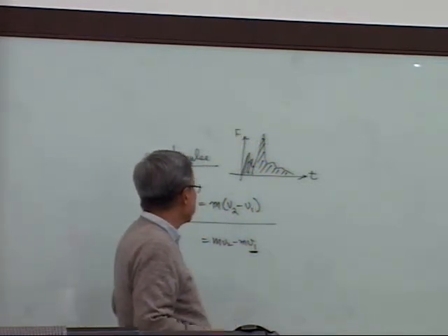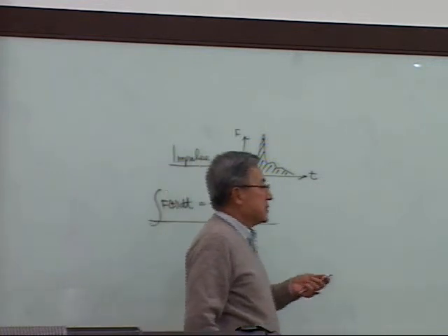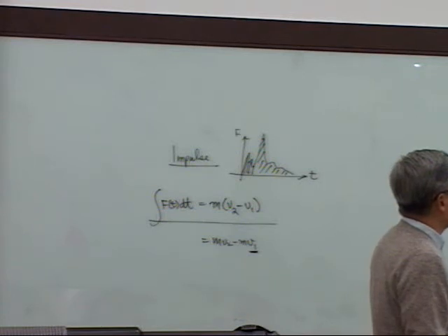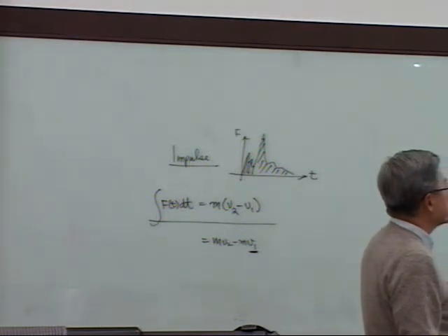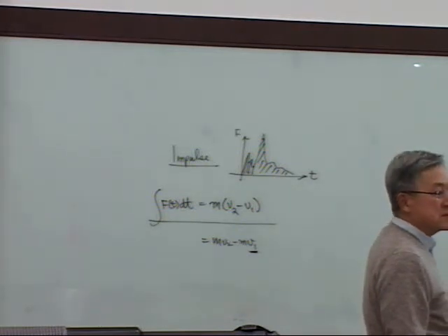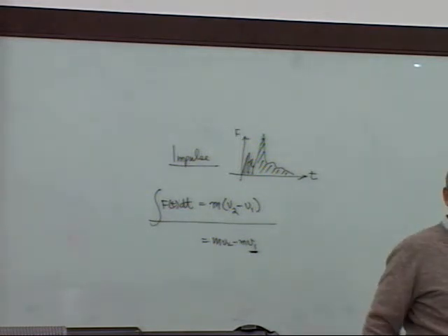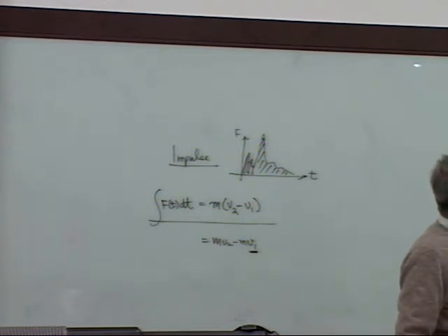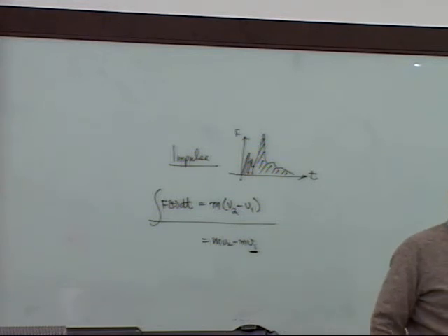So that's what I say: compute the plate momentum and the shock wave impulse. Shock wave impulse is what the underwater explosion can generate. The impulse is trapped in the water, and some of it is absorbed by the plate because it has flexibility there.